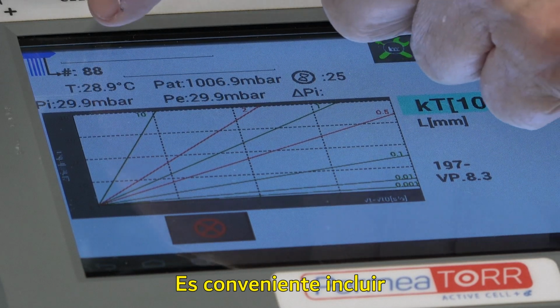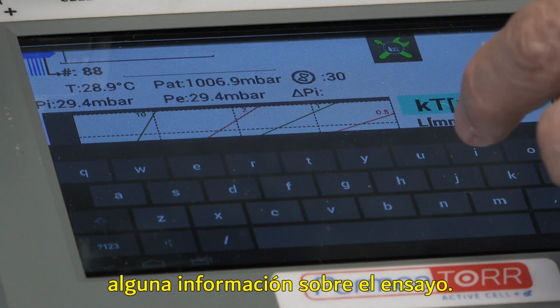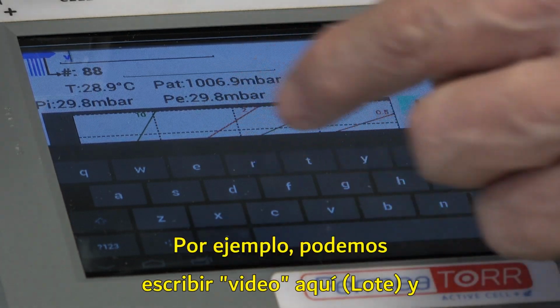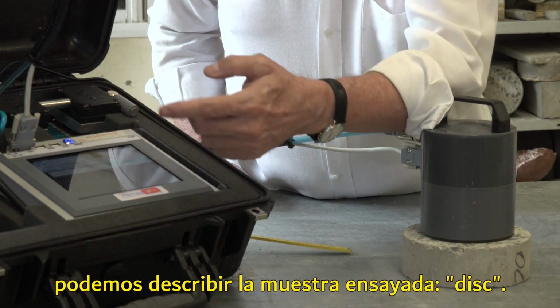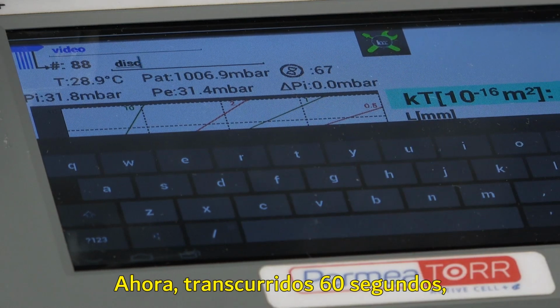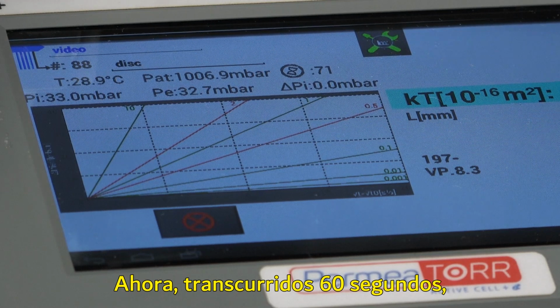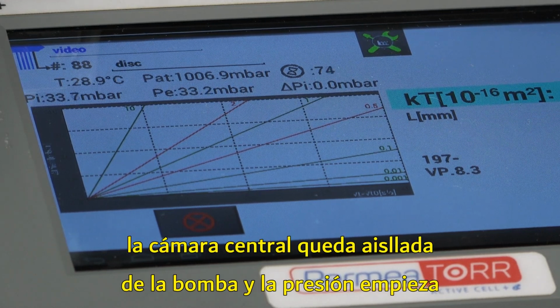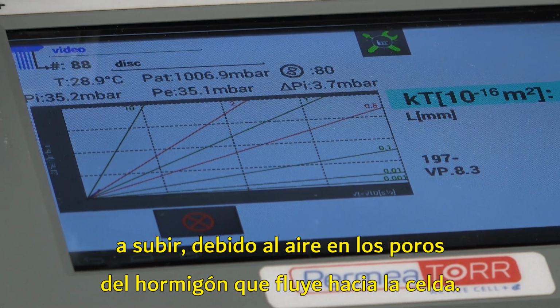Here, if we want, we can include some information about the test. For example, we can put video, and we can say, here you can describe the sample, which is a disc. Now, after 60 seconds, we have to press. After 60 seconds, now the inner chamber has been isolated from the pump, and now the pressure starts to rise due to the air in the concrete pores flowing into the cell.